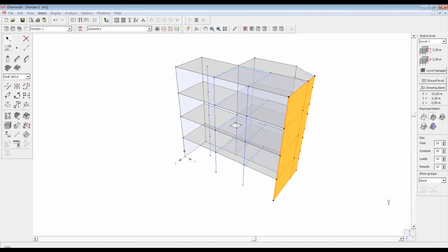I have completely selected the right wall. I can hide this, but that won't be wise because I want to add an opening right there, or I can show only the selected elements, which seems the most logical to do that. And all the other elements will turn invisible, they will be grayed out. So that makes it easier for me to draw the correct elements.